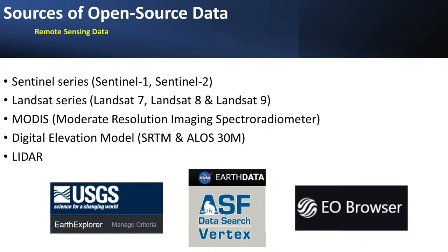Because with the 30-meter digital elevation model, when you're modeling floods, there's a lot that happens between every 30 meter in terms of elevation. So if you use LiDAR, you are able to develop and get high resolution digital elevation model, which improves your flood modeling. So the better the quality of the data, the more improved the results that you're going to get. So we should also aspire to get the highest resolution data that we can lay our hands on when we are modeling floods.